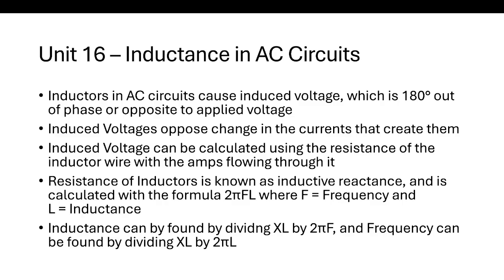And the resistance of inductors is called inductive reactance, which is calculated using 2 pi FL, where F is frequency, L is inductance. You can find your L by dividing XL by 2 pi F, and you can find F by dividing XL by 2 pi L.